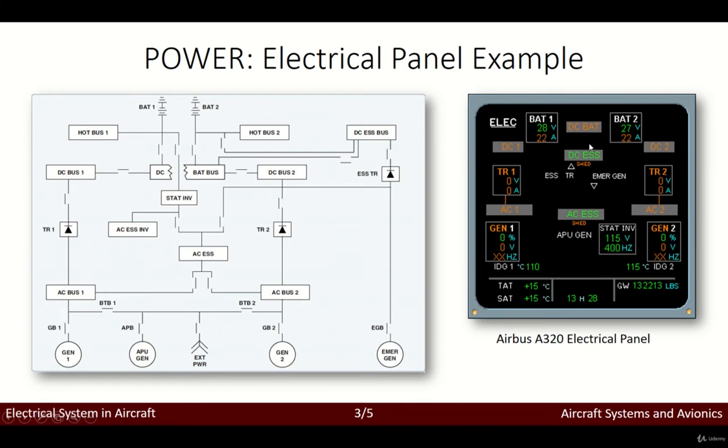On aircraft that are modified with the addition of an automatic switching system, which this could be, the switch does not need to be pushed in the case of failure of the AC bus 1. So this is a bit of the strategy used. There are many types of different strategies and algorithms that define when an AC ESS bus is working or not.